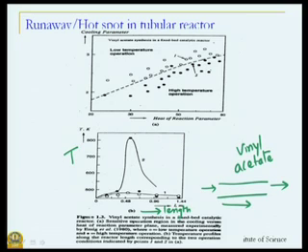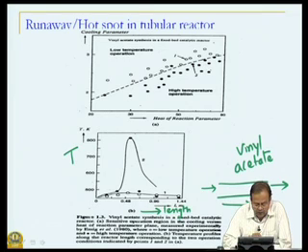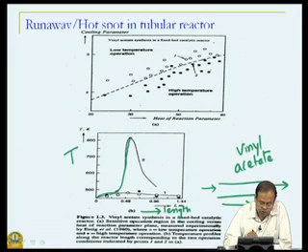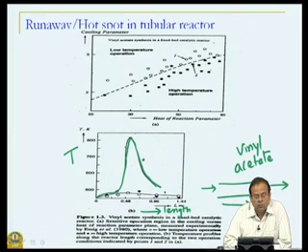of a nature such that if you have a low temperature operation, we are starting with a temperature of about 400 K and temperature remains well below 500 K during the entire reactor. It's about 450 K and so on. But there is something called high temperature operation, and we will try to analyze this situation in more detail. In a high temperature operation, if you look at this behavior, initially the temperatures are well controlled, but then something happens in our reaction and suddenly the temperature shoots up by about 300 to 400 Kelvin, and once again it comes down.